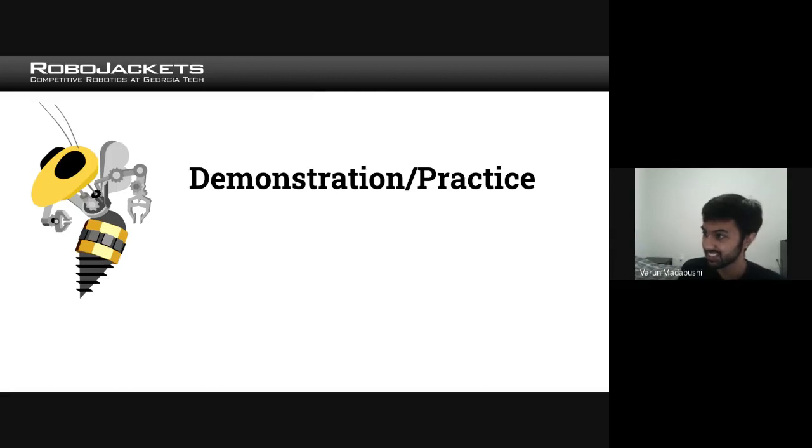So here I have some sample code that I wrote in MATLAB. There's a practice for DC motor sim and DC motor sim PID. The goal of this practice is that in DC motor sim, you take the DC motor equations and put them into the program, and then you should be able to simulate the motor and watch the state variables of position, speed, and current evolve.